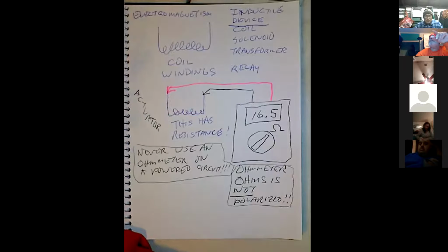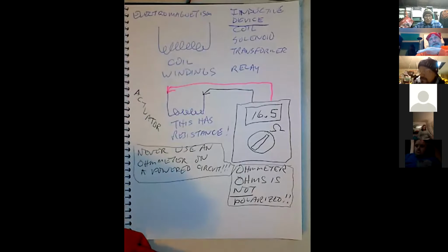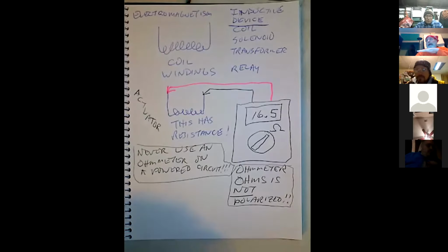Now, how does the evap purge control work? Well, what they're going to do is they're going to stick a vacuum to the fuel tank with a pressure sensor in the fuel tank, and they're going to draw down the pressure in the fuel tank. And then they're going to check to see if the pressure comes back up, signifying that there's a leak in the system somewhere. Make sense? That's why when you open your gas cap, it goes tss. On some cars, yeah. Now, how do you know if the purge control valve works? Because you've got a pressure sensor in the tank. And when the purge valve opens, what should happen to the pressure?